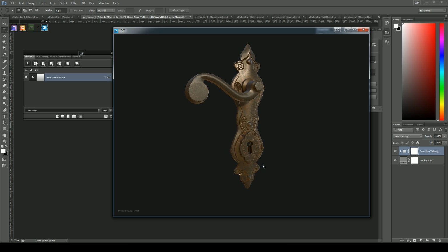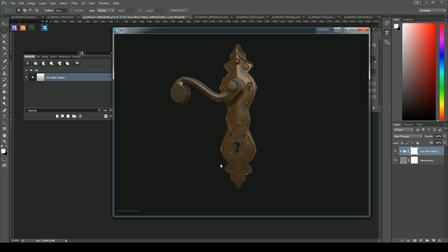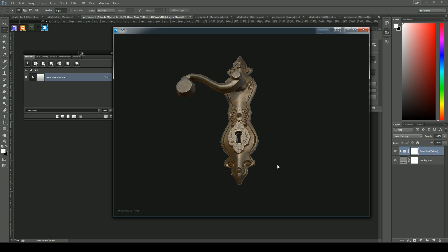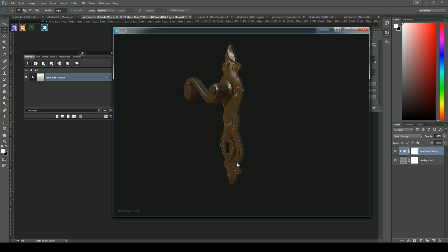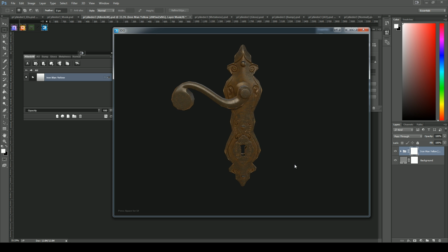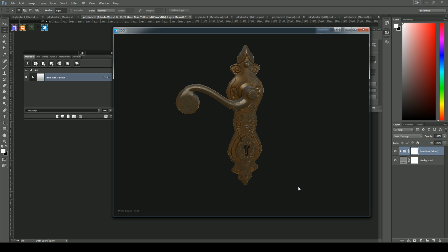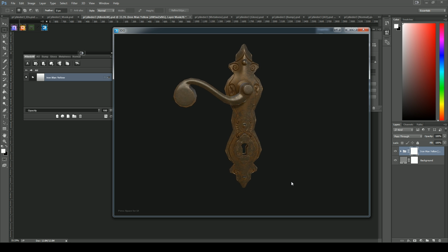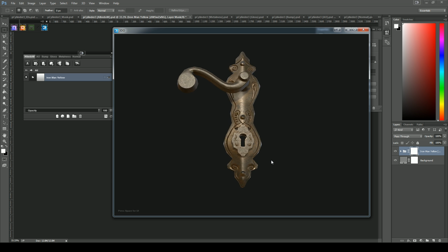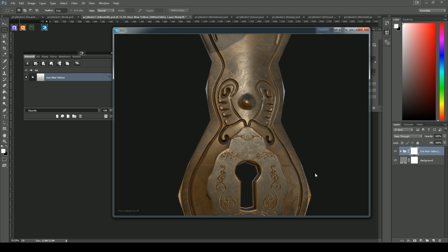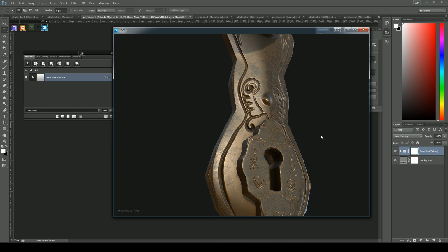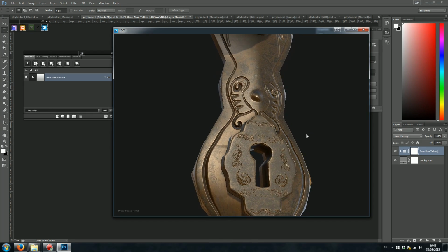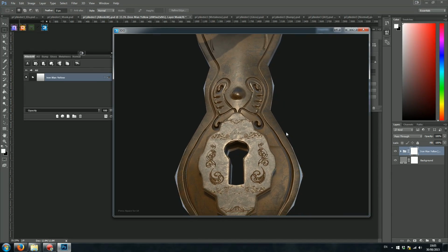And you could have just as easily have modeled a high poly model directly in Maya. Export all of that out as individual files and bring it into XNormal, which is pretty much an industry standard tool for doing your texture baking. At the end of the day, the whole point of making that high poly model is that we want to generate a normal map with a lot of extra information to go onto our model. A normal map is just a texture, and you can just do that in Photoshop if you need. It doesn't have to be done through a lot of complex high poly modeling. So it's important to understand that there's a range of different approaches.